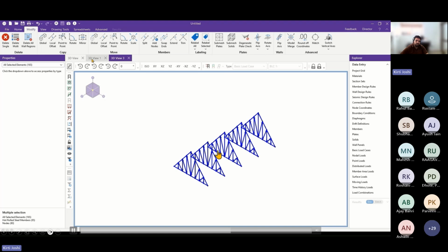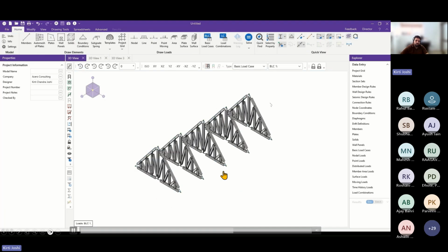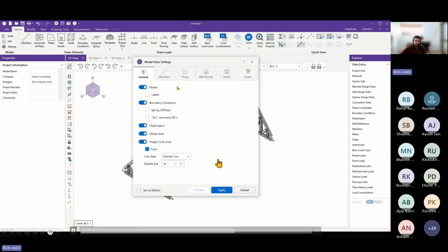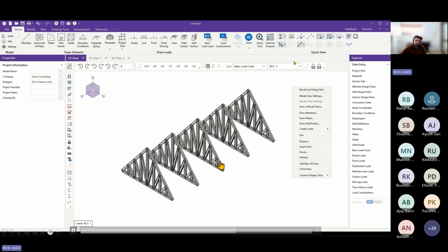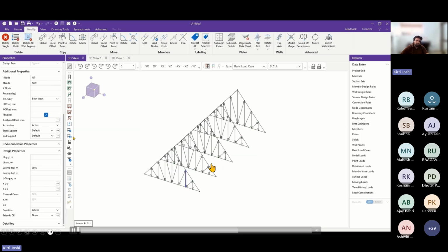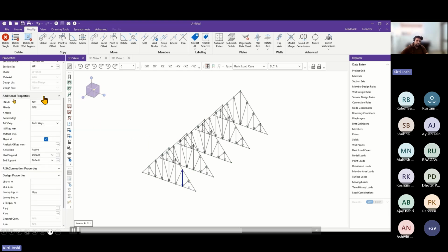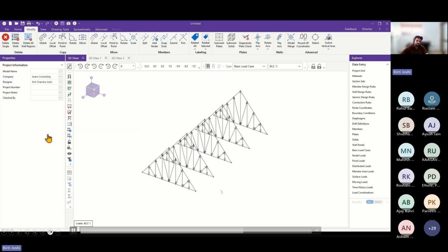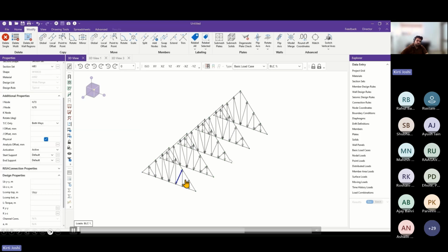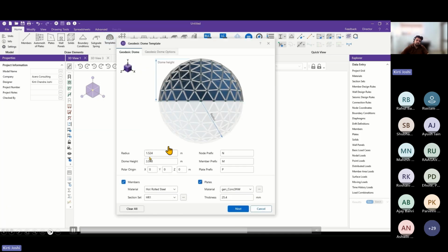Once you assign this, you can also set the effective lengths. On this length you can assign, and you can copy it into the different specified locations, so that it will create a truss type structure directly. This feature is quite interesting if you are working with truss type structures. As you can see, we can rotate its angle, or we can assign tension or compression members to the truss. All these features can be seen on the property toolbar.